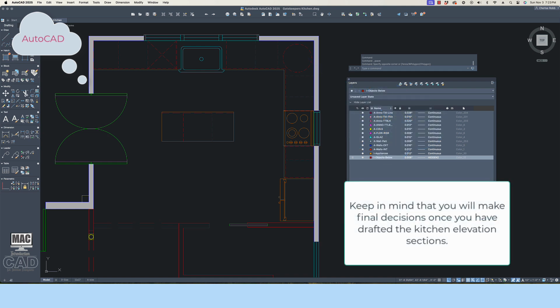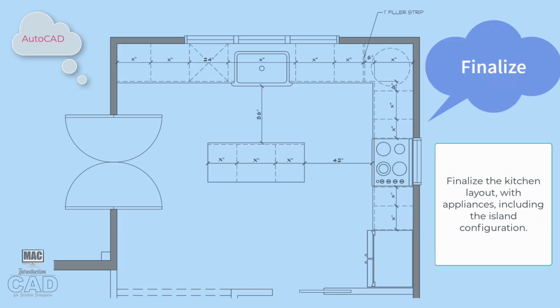Just because you choose one corner cabinet option at this point in the design process doesn't mean that is what the overall design will entail later on, in the final phase of the design process. For now, make the best educated guess by factoring in which cabinets, defined in the 3-inch incremental widths, will best fit in the space. Finalize the kitchen cabinet and appliance space plan. If you cannot divide up the length of space in an even increment of 3-inch widths, leave the additional footage at the end of the run of cabinets, such as where the freestanding refrigerator is located.